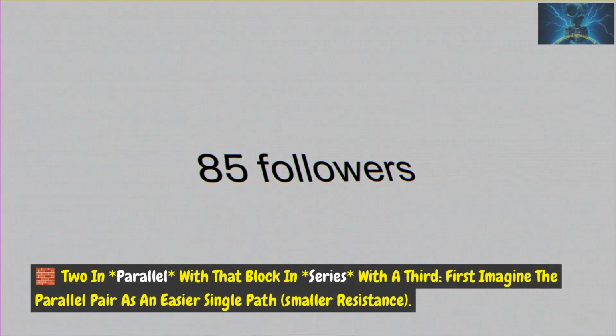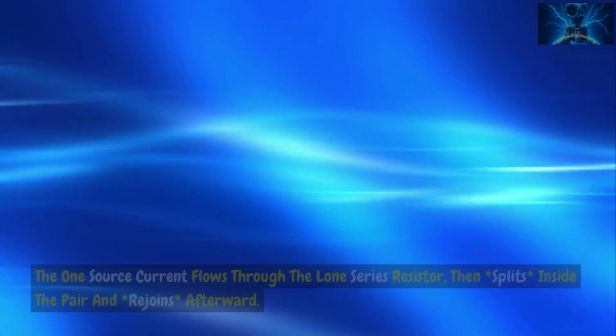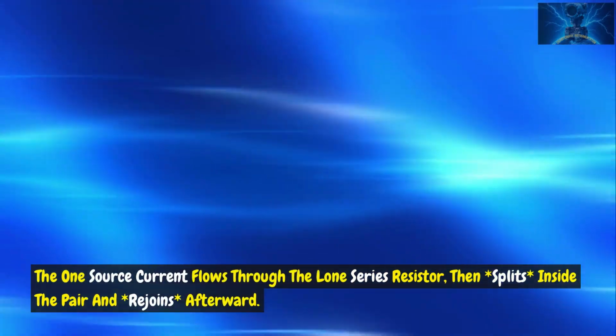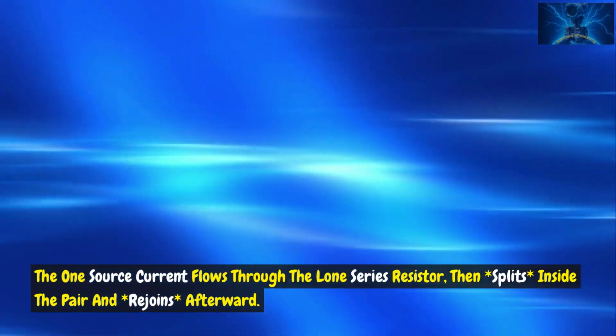2 in parallel, with that block in series, with a third. First imagine the parallel pair as an easier single path, smaller resistance. The one source current flows through the lone series resistor, then splits inside the pair and rejoins afterward.